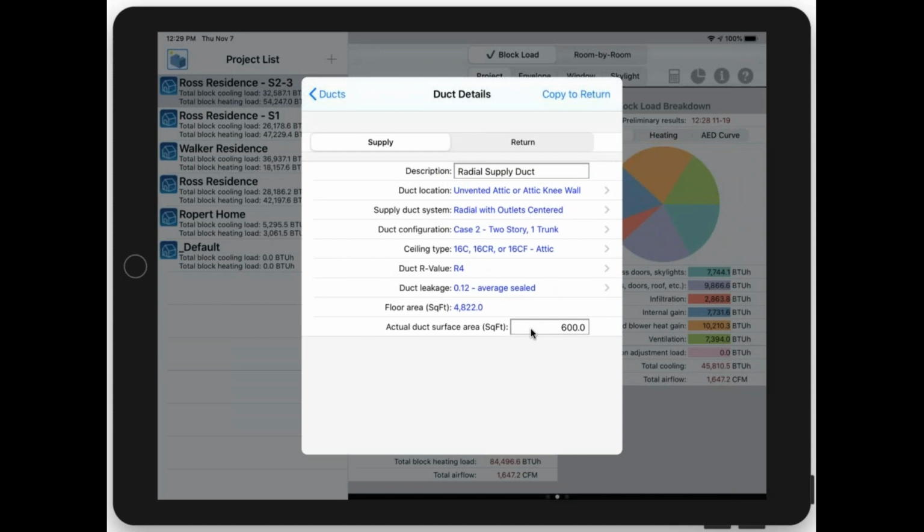Are you talking about the area of the duct? I know you said maybe cut it in half, but I'm just trying to get something I can be consistent with, kind of an average. Yes, I just noticed the ACCA Manual J handbook suggests 18% of your floor area, which, as you mentioned, and I see it all the time, is way too high.